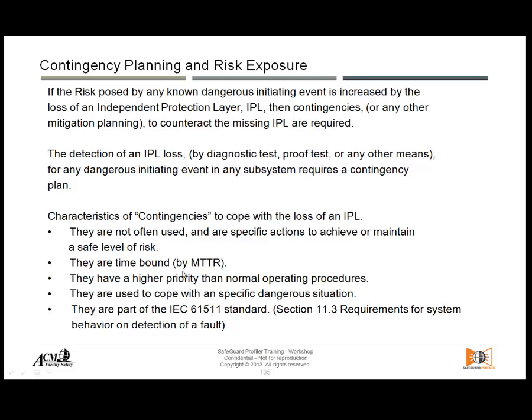And they are time bound. They are not forever. They are just interim, just while you're restoring your system to normal conditions and you want to keep running. And they have a higher priority than normal operating procedures. Of course, now they become a safeguard. So there's something additional that you're doing that is a safeguard. They are used to cope with specific dangerous situations, and they are part of IEC 61511 section 11.3, where they talk about requirements for safe behaviors on detection of a fault.